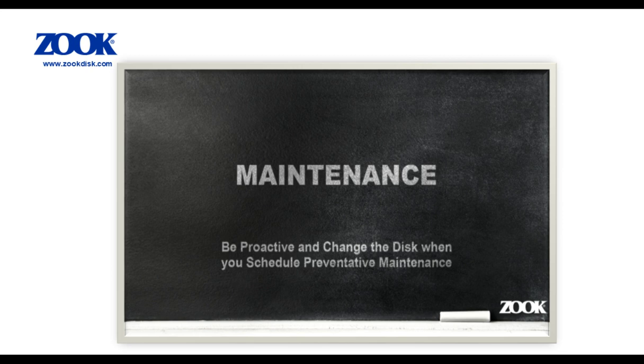People ask us all the time, how long will my rupture disc last? The truth is nobody knows, and scheduled preventative maintenance is recommended. Or if the process is down, take the opportunity to change out the disc. In absence of actual installation history, we suggest starting with a 1-year interval between scheduled disc replacements. We understand how self-serving this sounds, but it is better to have proactive preventative maintenance. The cost of replacing a disc is far less than the cost of unplanned shutdown and the resulting loss of product and production. There are no specific maintenance tasks that can be performed on the rupture disc.